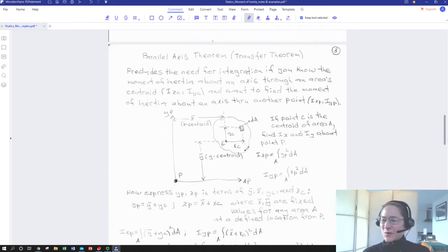Okay. Again, what if we need another axis? Because in case you haven't noticed, all of our examples so far have included something being rotated around an axis that looks an awful lot like it's going through the centroid, or assuming it's uniform density, the center of mass. So a lot of times we want to rotate something around something that isn't the center of mass. So we can always define a radius. So let's contextualize things to this example here in this drawing. So we've got a body that has a centroid at point C.